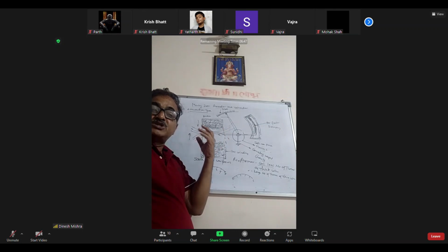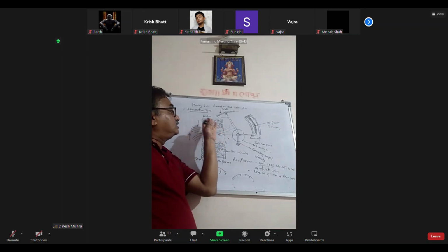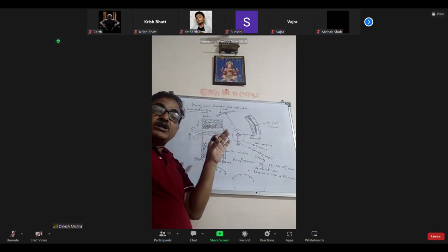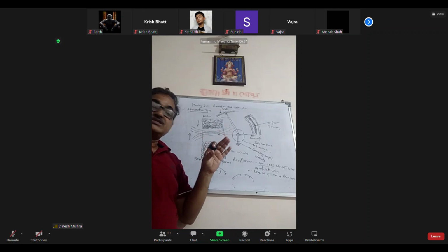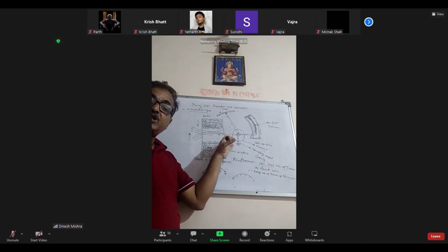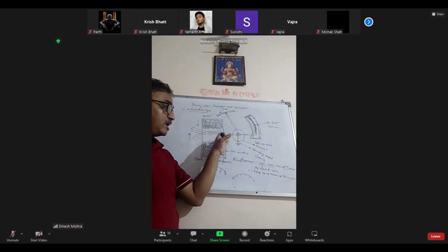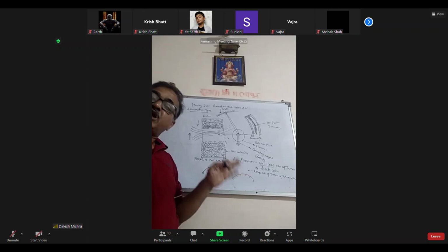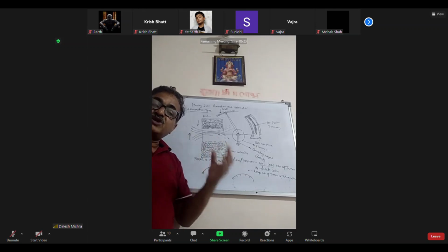This instrument has a hollow coil that is divided into equal parts. One soft iron piece is kept near the coil. Gravity control system is used for the controlling system, and air friction damping is for the damping system. This is the construction. What is the working?